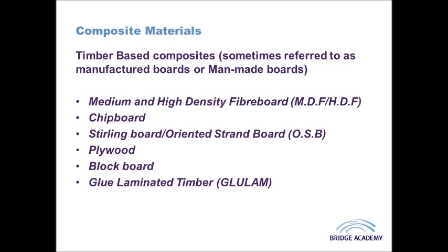Now, general benefits of using timber-based composites are the fact that obviously, unlike natural materials which have lots of moisture in them, have a tendency to perhaps warp or twist or bend. Because these are formed often, in the case of things like MDF, from particles or from tiny fibres that are pressed together, they're a lot more stable as materials, and in that sense they also have equal strength and toughness and things. They're almost a lot more of an engineered material than what a natural material is, so it's very likely that all along the board it will have very similar characteristics, whereas if we cut down a tree there could be weaknesses such as where branches attach to create knots in the wood and so on and so forth.